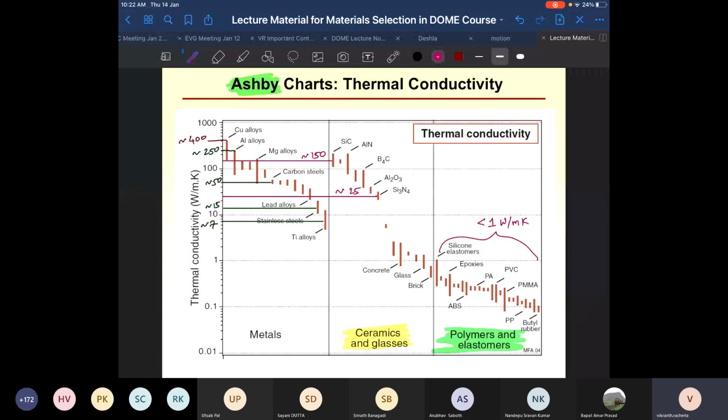If your system is very badly designed, then on the outside everything will look nice and good. If you touch the outer surface, it may not feel hot, but the inner temperatures might be continuously rising because you are unable to dissipate the heat, and eventually something is going to break down, because every material that you use has a certain operating temperature range.